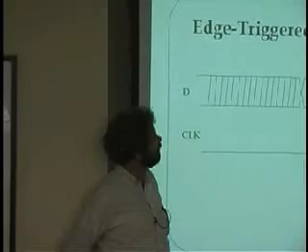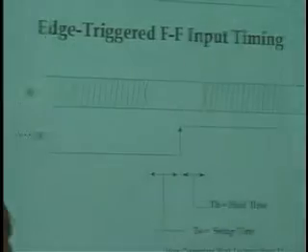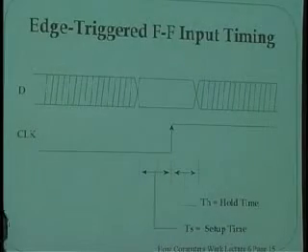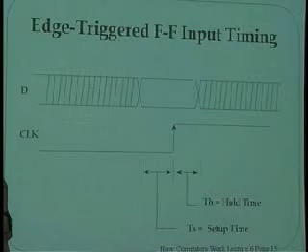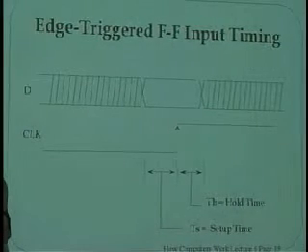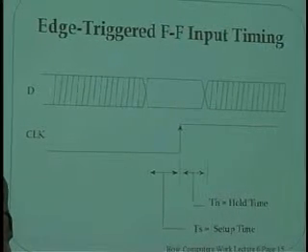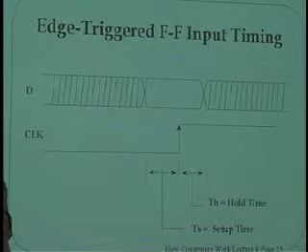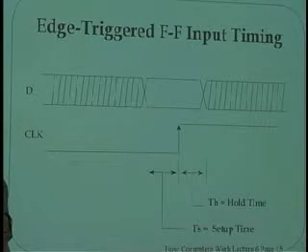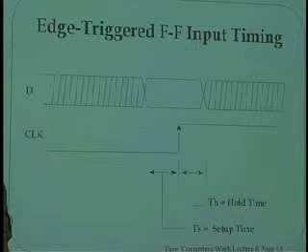Okay, what's going on here? It turns out that, yes? Don't you have the same problem with the clock, with knowing when the clock fires? Absolutely right, and we're going to talk about that too. The clock may fire at the wrong time too. And in fact, the oscillator that generates the clock is not perfect. And there may be some jitter. The amount of time it allows from one clock to the next may be somewhat uncertain.